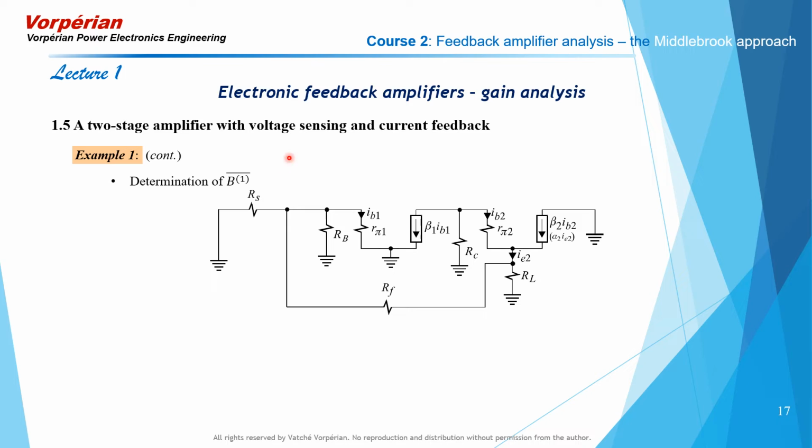Now we determine the inverse gain with respect to beta 1 with the excitation set equal to 0. To do so, we replace the dependent current source with an independent current source pointing in the opposite direction and determine the ratio of IB1 to IT.